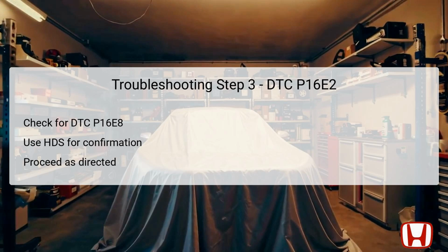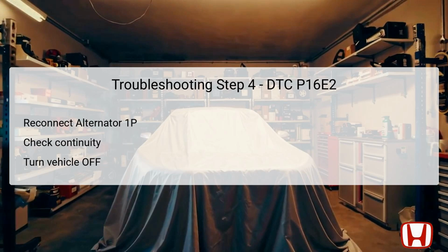Assessing this additional DTC helps to further isolate the problem and provides insight into whether multiple systems are involved in the communication disruption, which could point to more extensive issues within the vehicle's electrical architecture. Now the focus shifts to diagnosing connectivity issues within the LIN communication system.